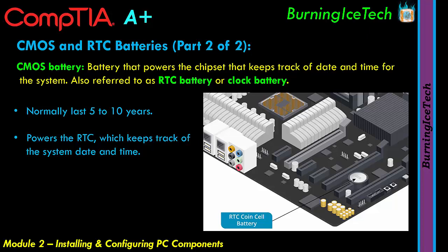I never buy them. I always have spares just lying around my house or the office. The most common example where I've seen this thing giving issues is if me or a user complains that their time is always wrong on a computer. If that's the case, I can almost guarantee you the battery on the motherboard's flat. They do normally last about 5 to 10 years. On average, it's more than 10 years. For most pieces I've dealt with, those batteries last for more than 10 years.